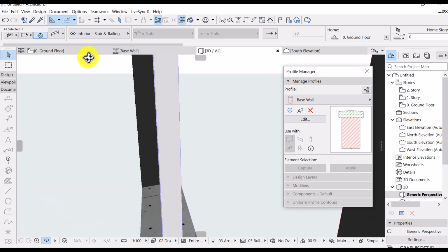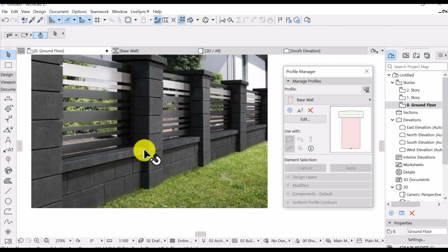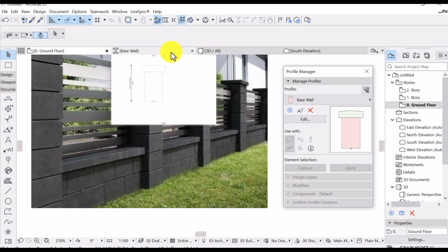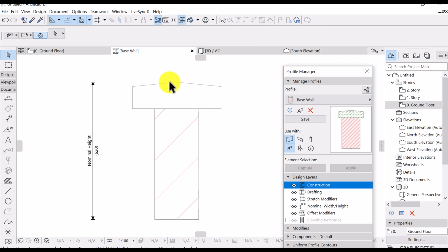Okay, but by the look of the image, you see there's a little bit of recess there. Mine is too much, so I'm going to go back here, and then instead of making this 300, I'm going to make it 200. I'm going to get rid of 100, and then make sure it sits on the center of the origin.